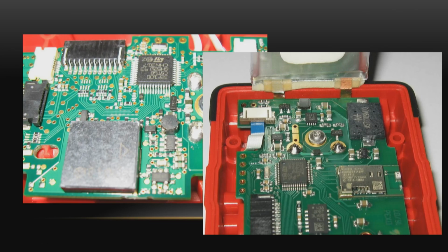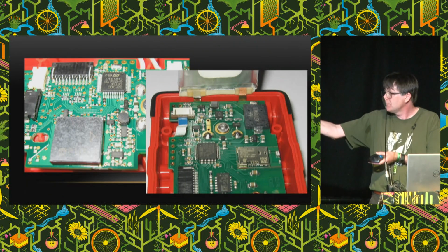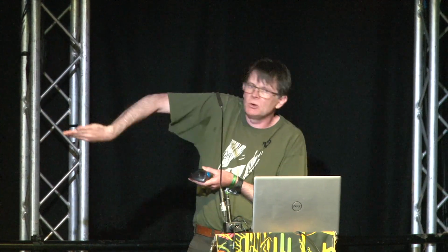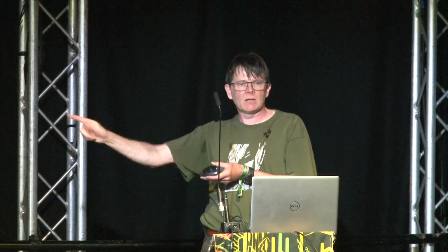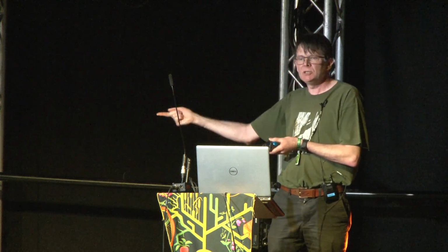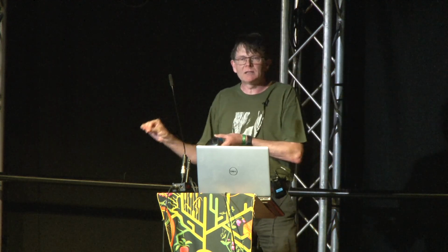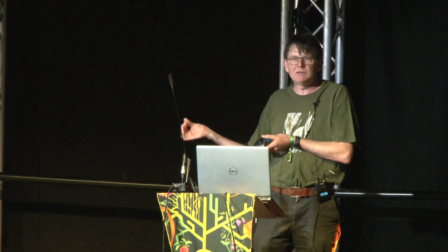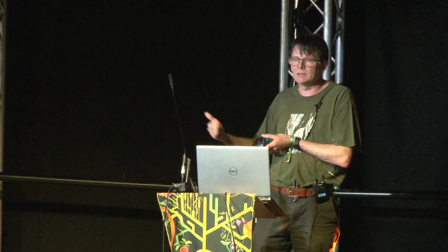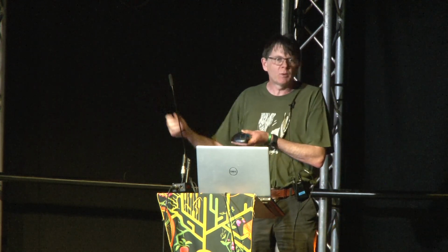and it would have a complex calibration process where, if you imagine the laser pointer being my hand, you would take a measurement of the same route with it rotated through four positions, like a barrel roll around the axis of the laser. With that calibration data, you do that for all the corners and faces of a cube from a point, and with all that data the calibration routine could then give you the accurate compass, clino and distance measure no matter which way up you held it.